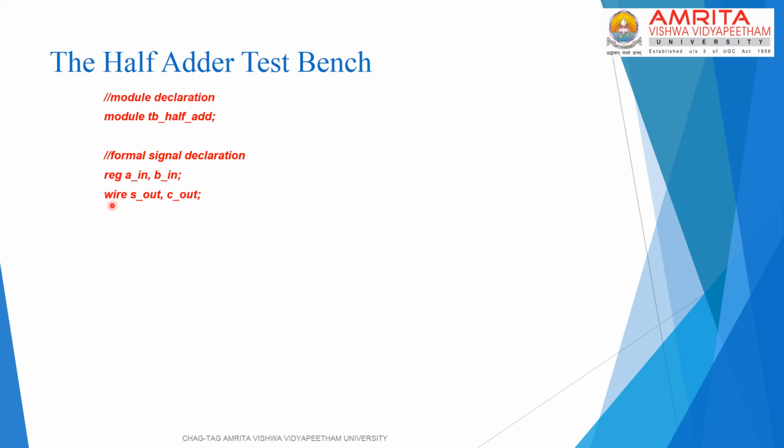Now the reg signal type is capable of holding a value. So the input signals which will be assigned logical values in the test bench are declared as reg. Whereas the signals S out and C out, which will be mapped onto the output ports of the half adder, are declared as wires because they will not be assigned any values on their own. They will rather be assuming the values which are driven to the ports by the device under test.